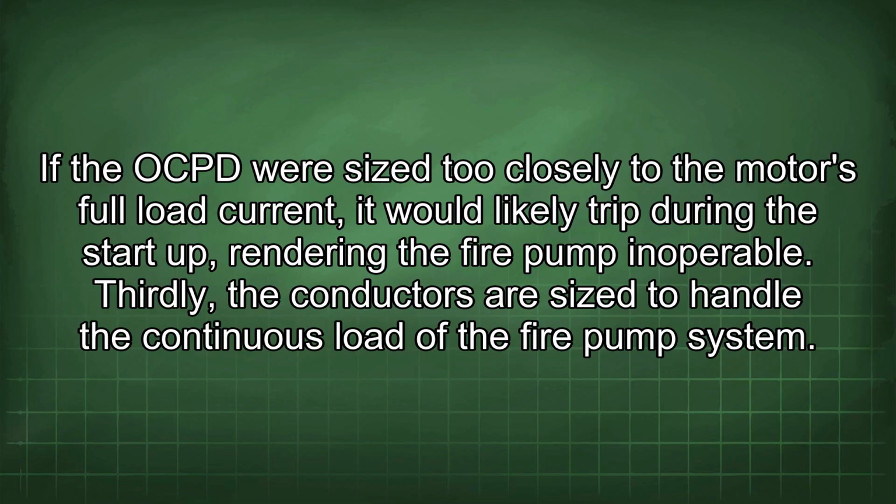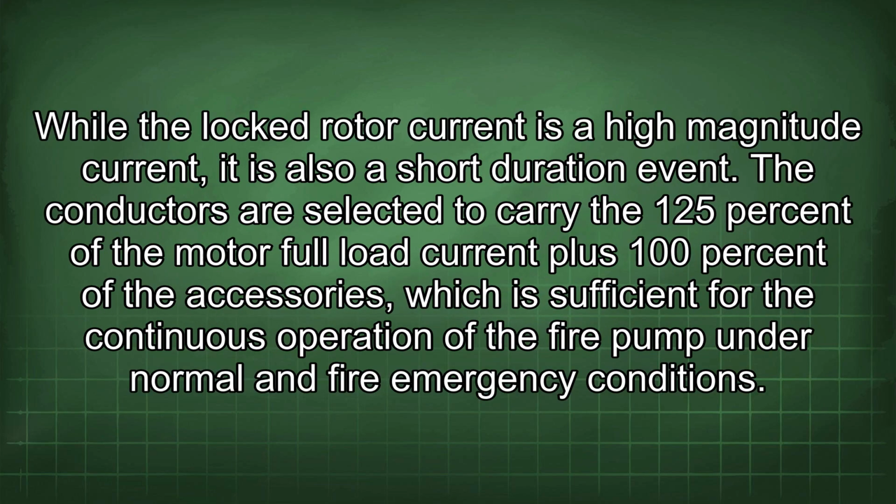Thirdly, the conductors are sized to handle the continuous load of the fire pump system. While the locked rotor current is a high magnitude current, it is also a short duration event. The conductors are selected to carry 125% of the motor full load current plus 100% of the accessories, which is sufficient for the continuous operation of the fire pump under normal and fire emergency conditions.